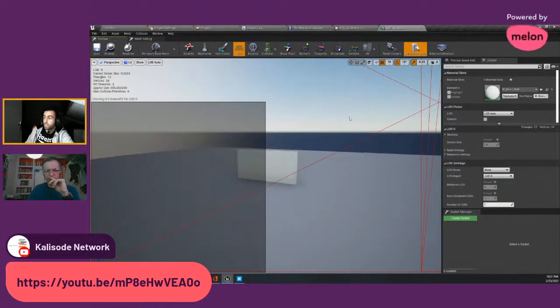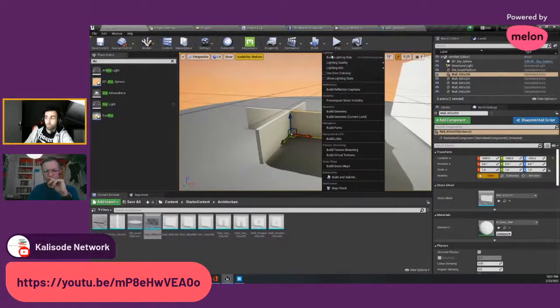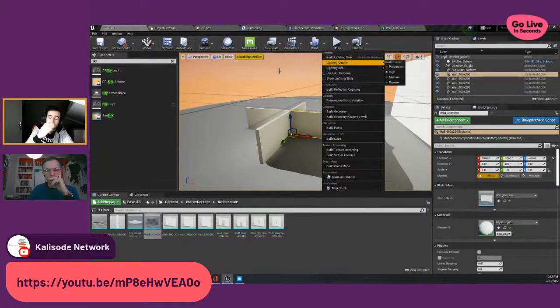that you will give the engine, which in this case there's no UV because the mesh is coming from the engine. But if you want to import a mesh to the engine, you will have to fix the UV first because the engine will then create another UV map for the lighting purposes. So if you want to bake the lighting, if you want to use this option, you have to fix all the UV issues that you are going to have. In that case, I would strongly recommend you to Google it because it's a lot of work and you will face a lot of problems, a lot of headaches, really.